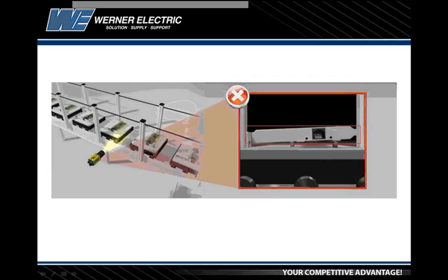People in the plastics injection molding industry, if anybody on the call has injection molding presses in their factory, we've sold quite a few vision sensors, the lower cost vision system, to look down at the die so that when the injection mold opens and it's supposed to eject the parts, it just verifies that all the parts are ejected, because if you ever close a mold onto a hard part that wasn't ejected, it can damage the mold.